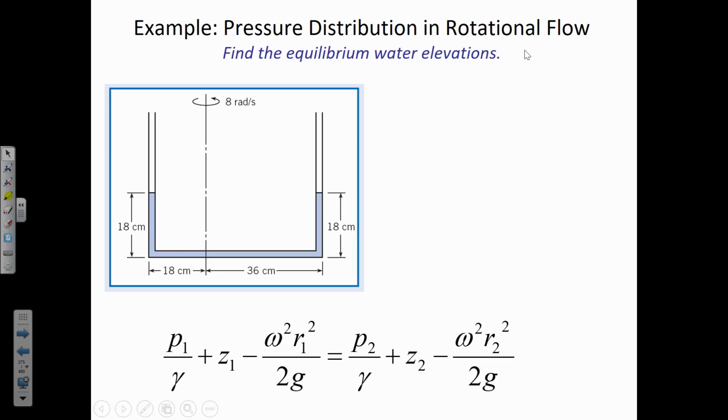You just set where your P1 is, that's going to be your datum. So you're going to say, let this be the elevation datum. Okay, so Z1 is equal to 0. Then Z2 is going to be an unknown. Once you get to your delta Z, how do we get the delta Z? Delta Z is basically Z2 minus Z1, right? So you could manipulate the equation through Z2 minus Z1, solve for what that equals to, and then add it to where it is initially.